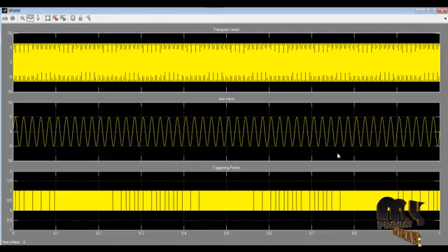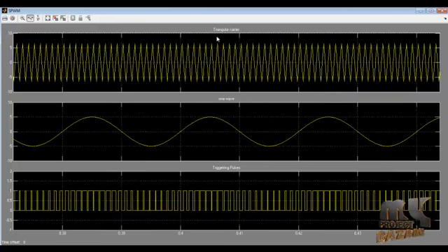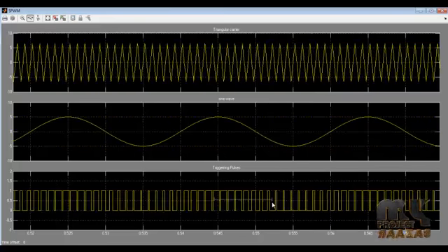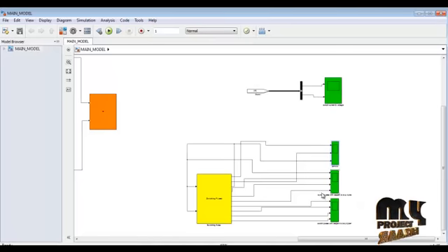Next this is the main part of this project, the switching pulse. We use PWM pulses. This is a triangular carrier, and this is our sine wave with an amplitude variation of 5, and this is our switching pulse with different duty cycles, the amplitude being the same but with different duty cycle ranges. You can see this block is very tiny, this one is a little bit bigger, another is too big, and then the duty cycle ratio gradually increases and decreases. So this is randomly getting that process.